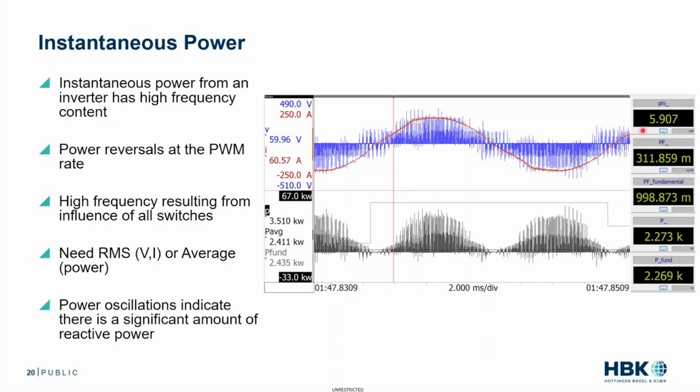So if we look at the calculations, and this is based on a 200 kilohertz filter rate, so 500 kilosample sample rate. Our phase angle, again, this is of the fundamentals, because that's really the only way to calculate it, is 5.9, so relatively low phase angle. But our power factor is 0.311, because this is power factor calculated with all those harmonics. Power factor of the fundamental is 0.998. So what's the difference here? And the difference is switching frequency.